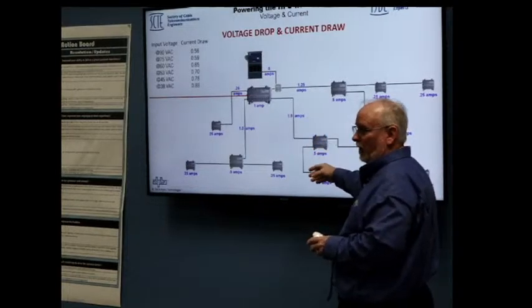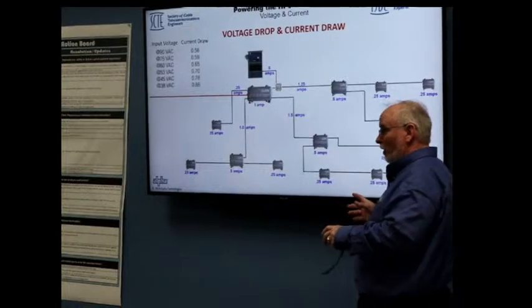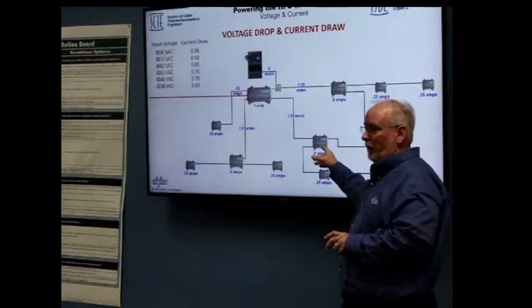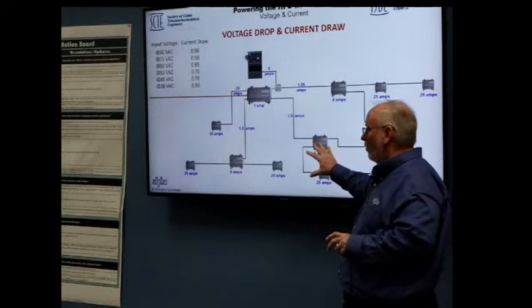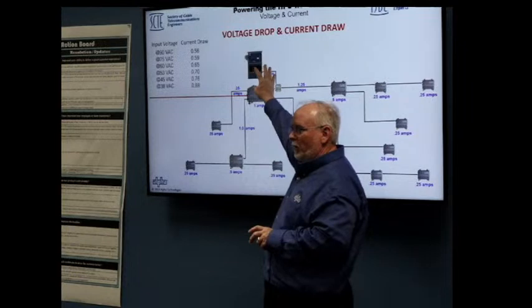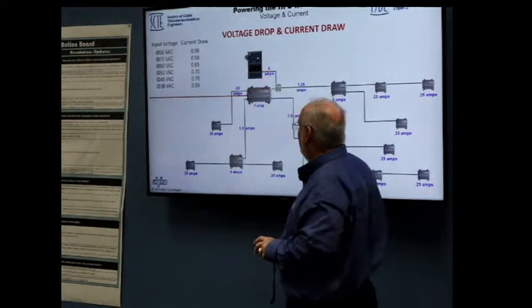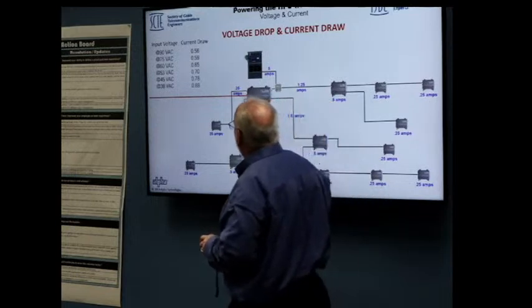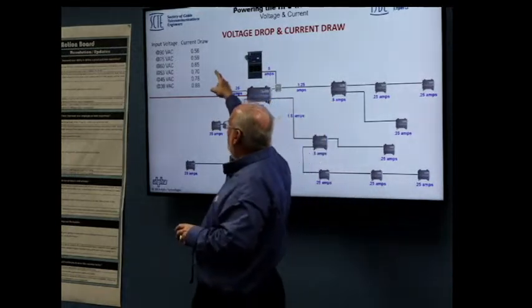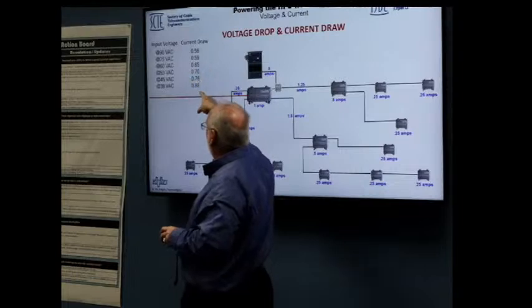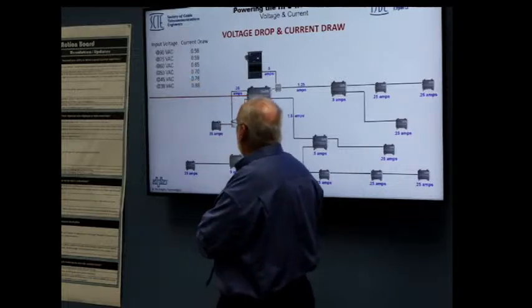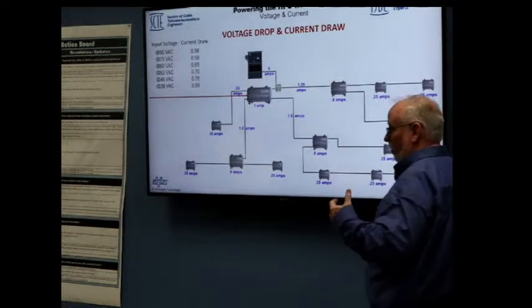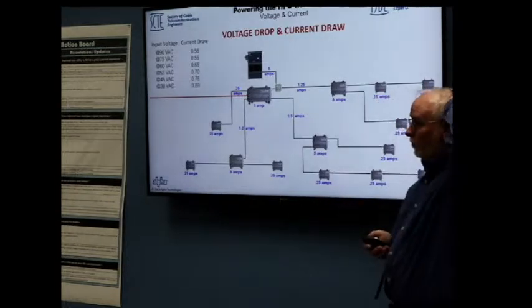They will cut off at 45, not because they can't run lower, but because the MSOs have said if you run lower than 45 volts, you'll create such a current draw that it would cause a problem for my powering circuit. Right? So when we add all these up, a device that pulls about a half an amp at 90 volts will pull 0.88 at 38 volts. And when you're looking at a node or an RFI node, you're looking at like 2.1 amps.